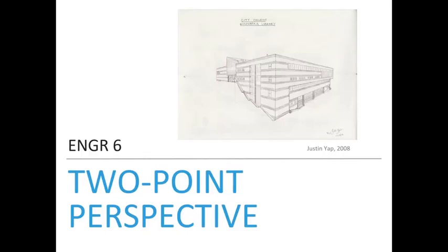The one-point perspective sketch is typically used for objects that have one characteristic frontal direction, and other directions are not as important. When an object has more than one direction that needs to be drawn, the two-point perspective method is preferred. If you construct an XYZ coordinate system, the z-axis is in the vertical direction on the image plane. The x-axis extends in the forward right direction, and the y-axis is in the forward left direction from the